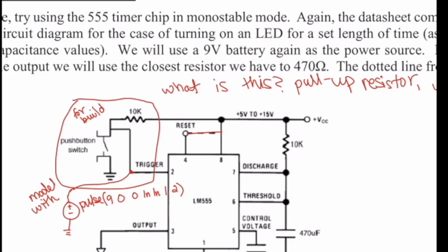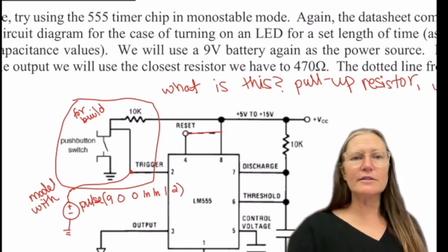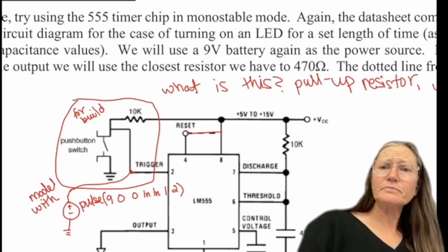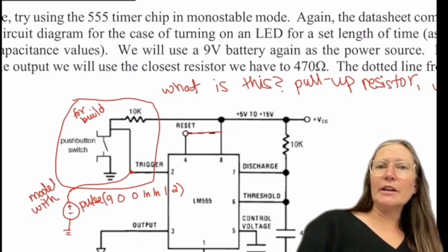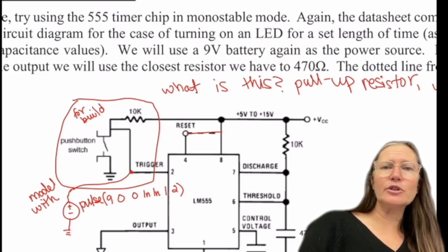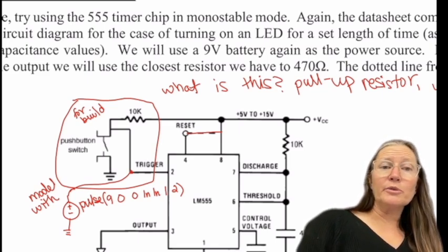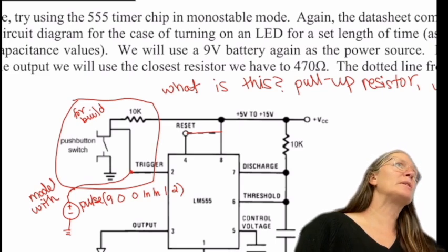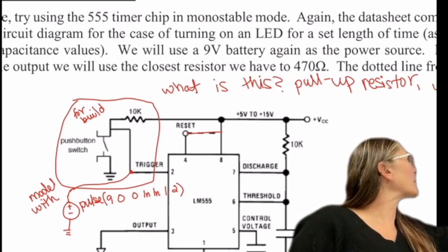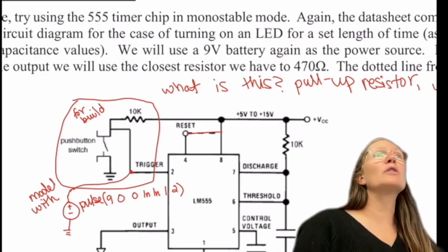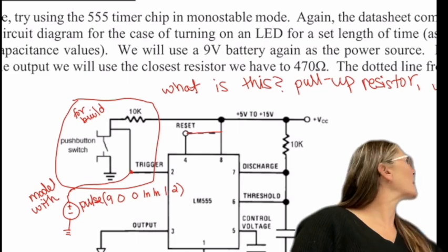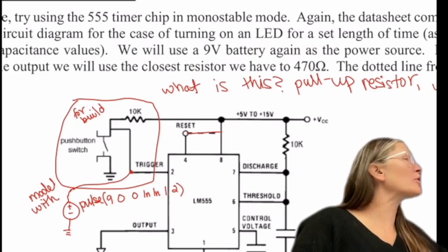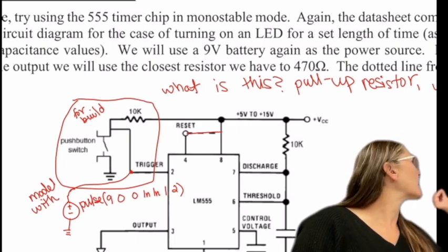Good things for me to point out. I forgot to also mention, you can find the traces if you label the wires. I find it typically easier in LTspice to use the little probe. As you see when I go next to a wire, it has a little probe, like a digital multimeter probe, red. Wherever I click, that's going to compare it to ground. When it changes to the current, that means through the element.